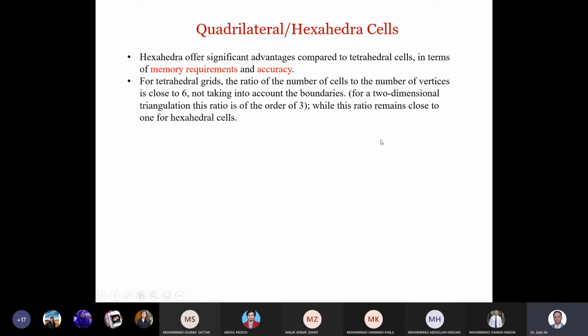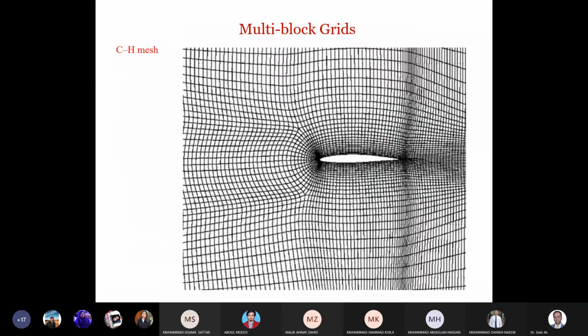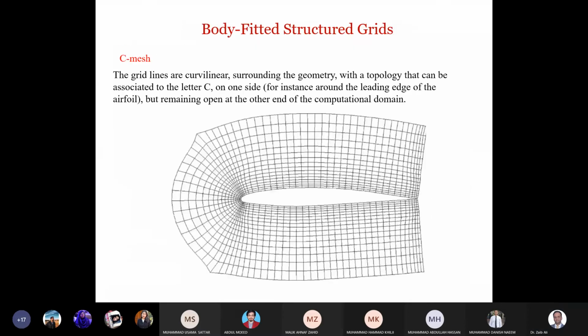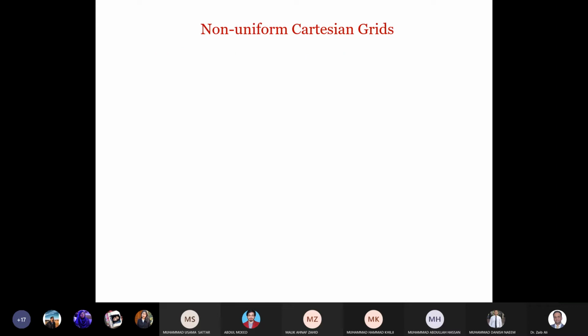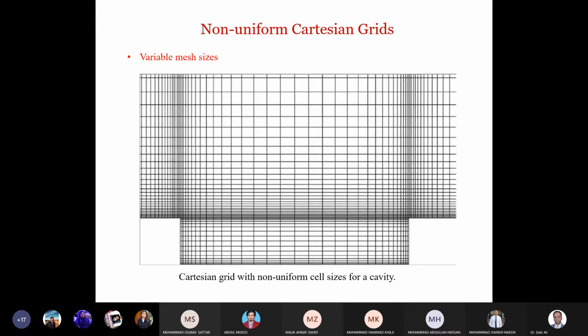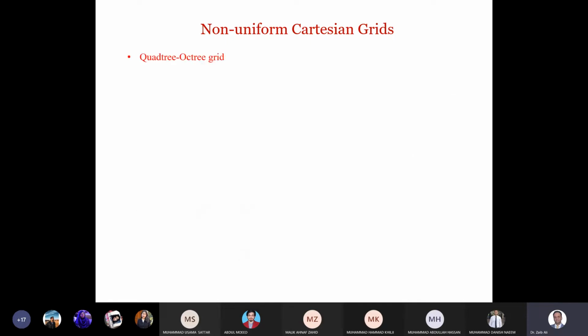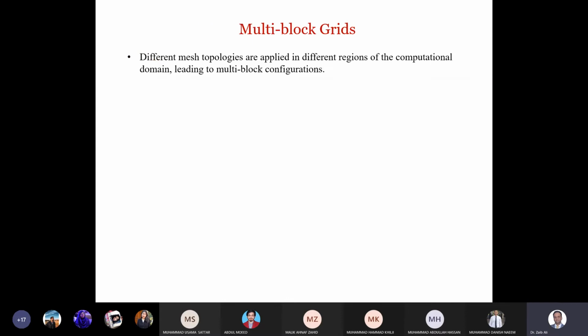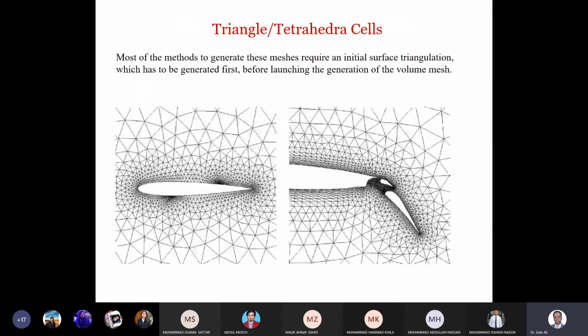And in the case of a structured mesh, you can also see the size is decreasing gradually. So you should avoid directly jumping from this size to the next layer of about this size. This will create a sort of convergence issue, because the numerical scheme or solver will not be able to handle it efficiently. Something which you should keep in mind.